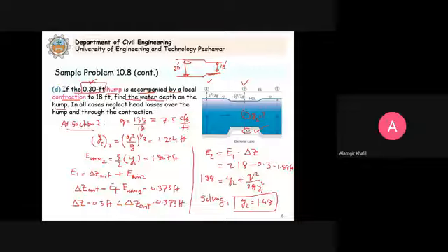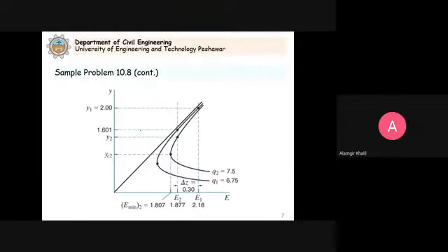to 1.48. Now to summarize what we have done, you see that this Y1 was given as 2 feet. Then we come here, so this 2 feet, we proceed along this line here, and this is the specific energy curve, this one here, for Q1 equal to 6.75. Now from here in part B of this question, the hump that was provided with 0.30. Because it reduced the specific energy, you see that from E1 with 0.3 we come here. So we come here to this E2, and then from this E2 we proceeded, because critical depth did not occur, we proceeded here, and this was the answer.